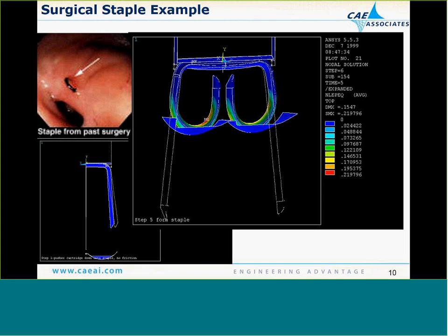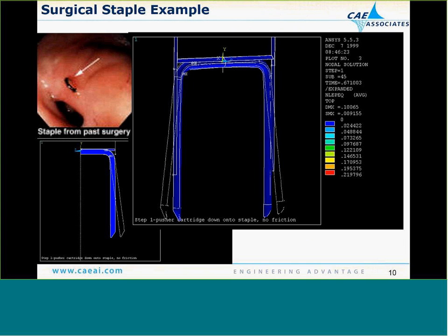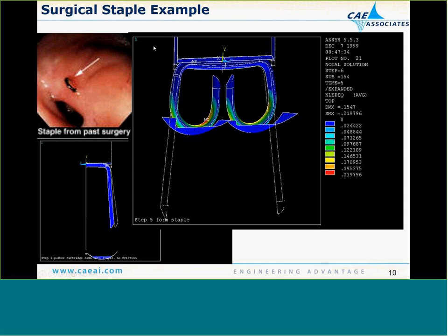You notice that in this particular example, the item on the right deforms basically correctly. The item on the left is one that buckles. It's something that we can predict with a plasticity model, setting up an imperfection in the model to demonstrate this plastically induced buckling phenomenon.